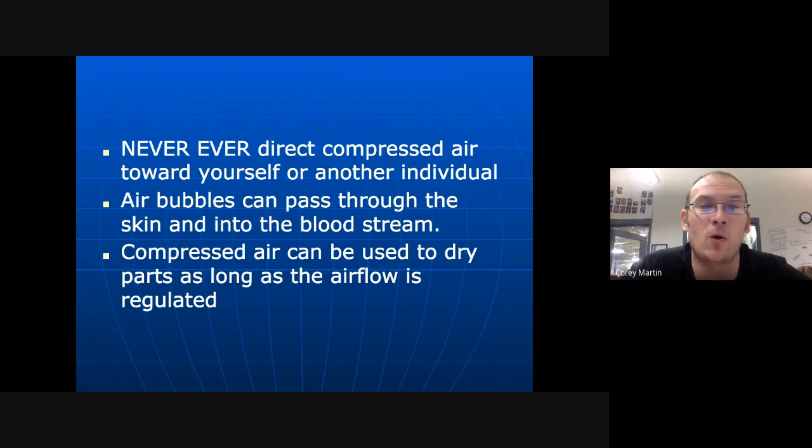So we would have to walk over to the regulator, turn the pressure down, dry off our component, and then turn the air pressure back up, because 25 or 30 pounds of air pressure will not run an air hammer or an air impact. So again, this right here, the very top line, if I catch you doing something like that, you will find yourself out of the shop, most likely permanently. Do not do it.